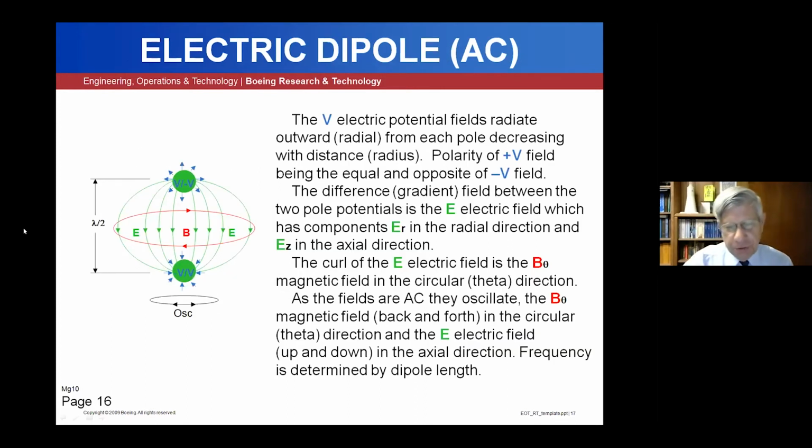So starting with the electric field, AC, going back to the textbooks, you still have the same charges separated by the distance, which D now becomes a half wavelength for the AC electric side, where it didn't matter on the DC side. And because it's now oscillating, you have a B field that is generated in the axial direction or circular, however you want to look at it.